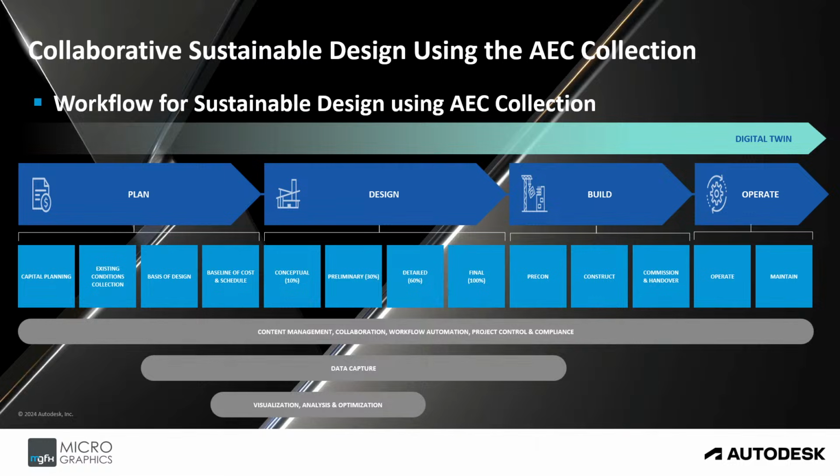Design development stage will be done in Revit. Import your Forma pre-conceptual design into Revit with your Civil 3D site model with geo-referenced data. Then collaborate this model. The collaborative model is then brought into Revit where the detailed architectural modeling, material assignment, and schedules are developed.